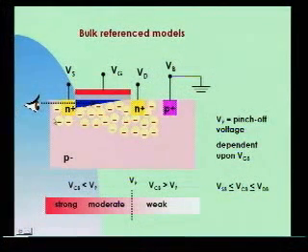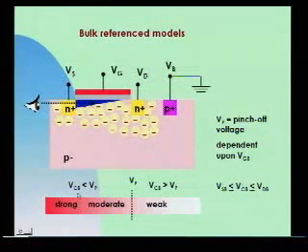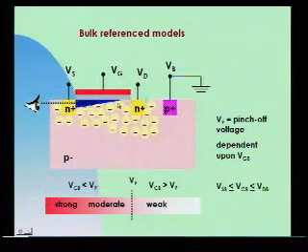the point of view emphasizes the control of the charge distribution by the channel voltage, and so to analyze the inversion level, we will compare the channel voltage with another parameter, the pinch-off voltage, which is dependent upon the gate voltage. Okay? Each point of the channel may be in strong or weak inversion.